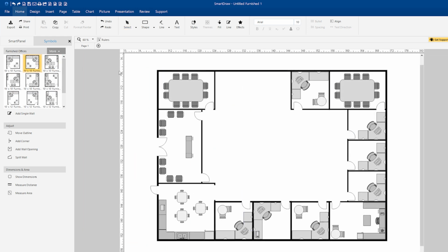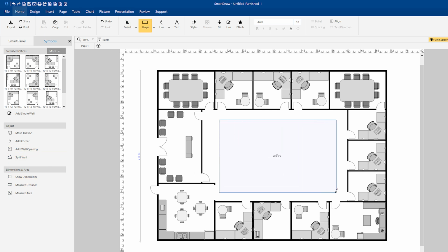If you add a room to a house or building, it snaps into place and the walls overlap seamlessly. The Measure Distance and Measure Area tools let you make measurements simply by clicking and dragging. As you make these measurements, the outlines stay there for you to use as a reference in your layout. Just select them and hit Delete if you want to remove them.